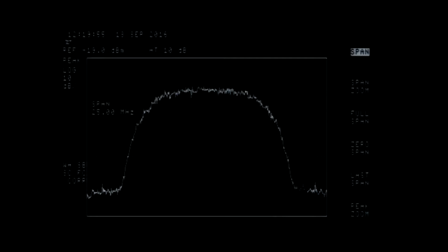Finally, I thought I'd give you one last shot with everything turned up full. This is DVB-S2, 32APSK, 9/10 FEC. Transmitted bitrate is 53.4 megabits per second. CPU usage 42% on my PC.